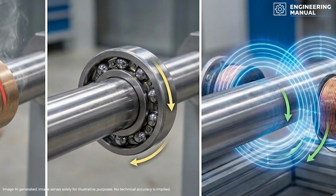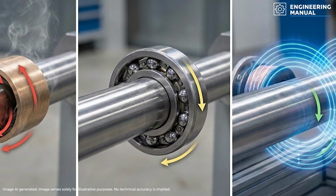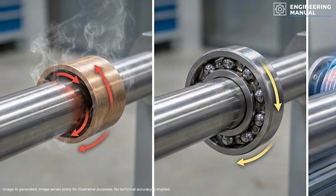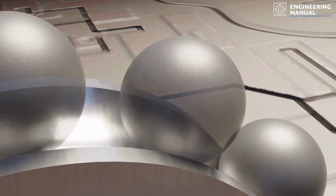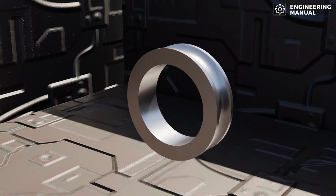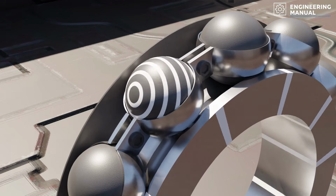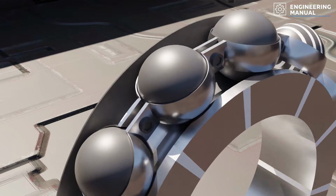The obvious solution would be to let the shaft slide inside a hole, but sliding surfaces generate enormous friction. Every revolution wastes energy as heat while continuously wearing away both surfaces. Engineers solved this centuries ago by replacing sliding with rolling. Instead of allowing the shaft to slide, hardened steel balls roll between two precisely machined raceways. Rolling friction is orders of magnitude lower than sliding friction, allowing machines to spin faster, consume less power, and last dramatically longer. That sounds like the perfect solution.